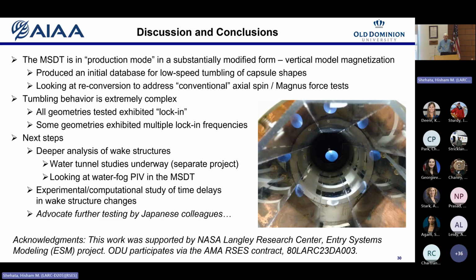Mark Schoenberger was one of the people that tried to reconstruct from the video, but it starts at a higher Mach number than we're at. It's all transient, so as it's plunging through the atmosphere, density's going up, Mach numbers changing. There's not really a clear comparison. So I guess the answer is sort of no. We looked at it, but I don't think you can compare one to one. And it was a more complex motion because it was spinning about its nominal flight direction, as well as apparently going end over end. So it's more like a wobble rather than a pure tumble.